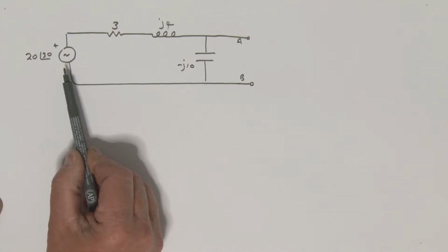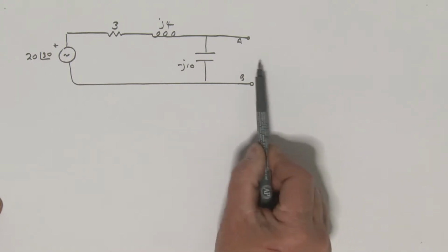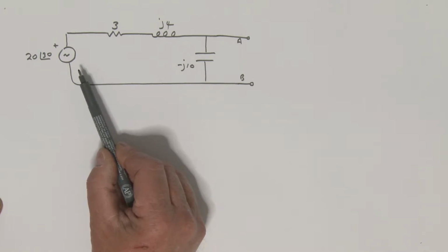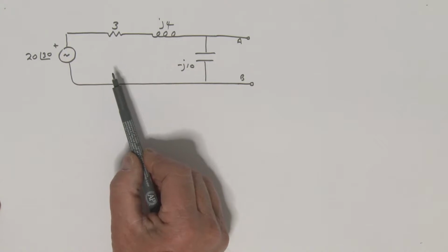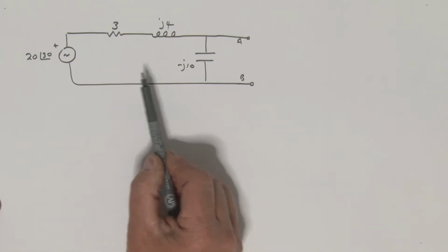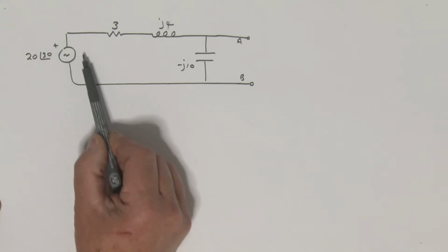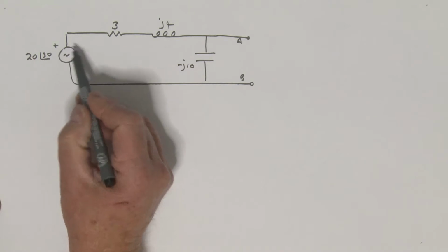And if you remember when we were looking at DC circuits, we said that we could look in at terminals A, B, and zero all internal sources if our circuit basically comprised of what? Independent sources. Well, the same is really true here. And so we could really zero this source. So let's just redraw this circuit with this guy zeroed.